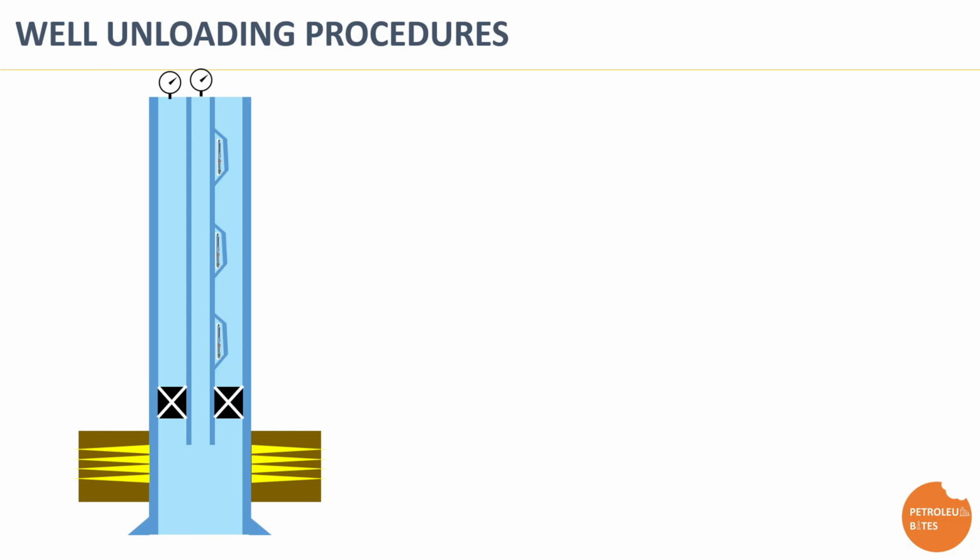Unloading a gas lift well and preparing it for production follows a defined sequence. The process begins with the well in a static condition, filled with the kill fluid in both tubing and casing. All gas lift valves are installed and initially set to the open position. Gas injection starts through the casing, displacing the kill fluid from the casing into the tubing via the open valves.